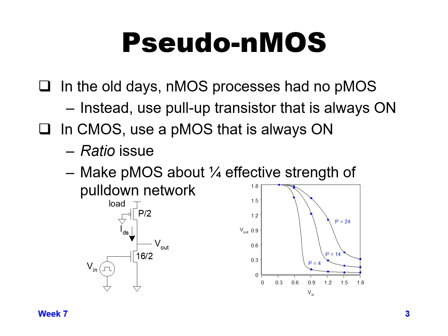If the NMOS is size 8 and the PMOS is size 2, keep in mind that the PMOS is half as strong per unit length or width as the NMOS. So an 8:2 ratio as far as effective strength is actually going to be an 8:1 ratio. So the NMOS is going to be able to pull pretty well down toward ground.